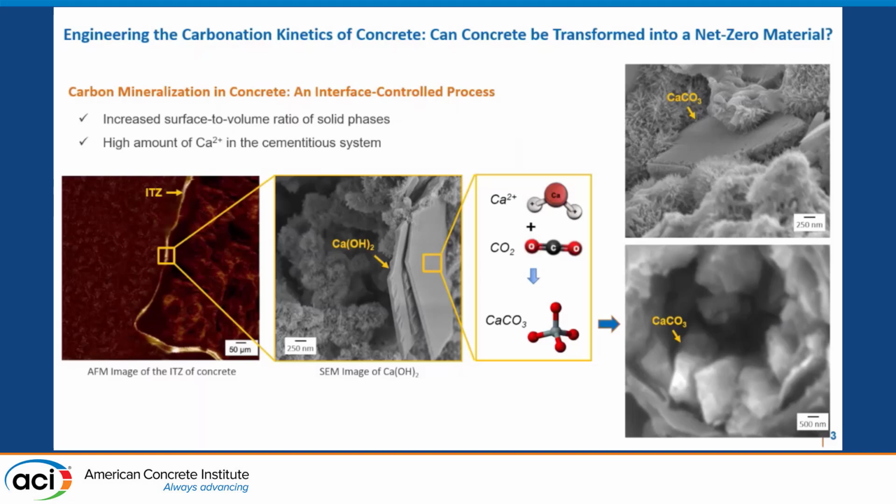However, we need to consider out of the box, different strategies. We need to engineer the carbonation kinetics. The material can do so much the way it is manufactured with all the inclusions, supplementary cementitious materials, limestone, everything.